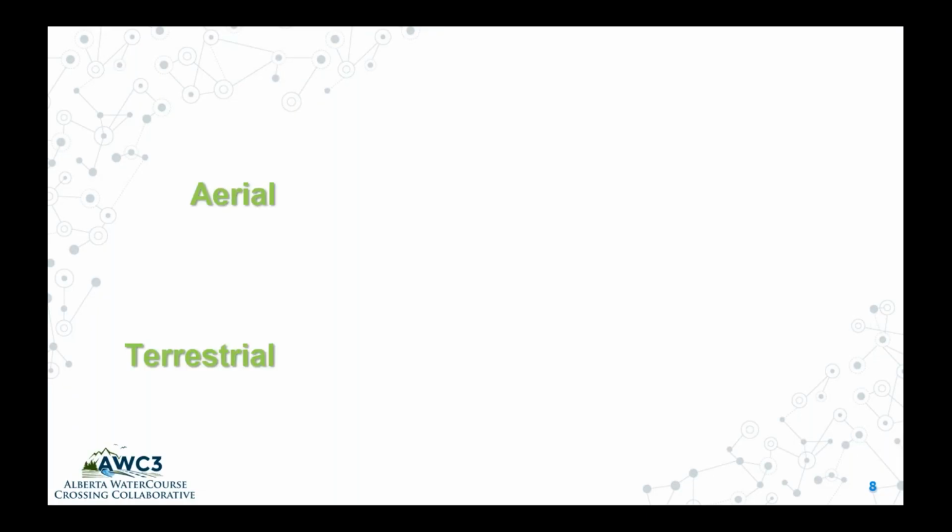Now, there are two basic types of LiDAR, aerial and terrestrial. Though there is a third type, which is the satellite or spaceborne, which covers large areas mostly for meteorological purposes. The industry in general uses these two types. Aerial LiDAR has been in business for almost 20 years, and most of us are familiar with it. It is of basically two types: the one used for land, that is topographic, and the one used on water bodies, that is bathymetric.